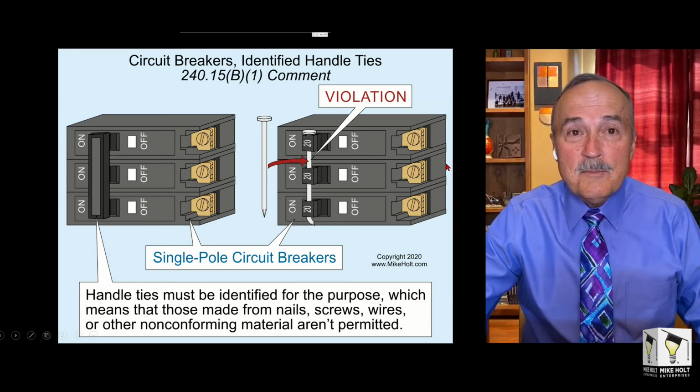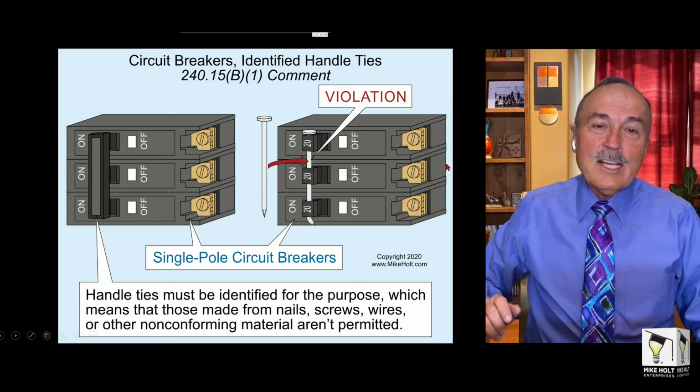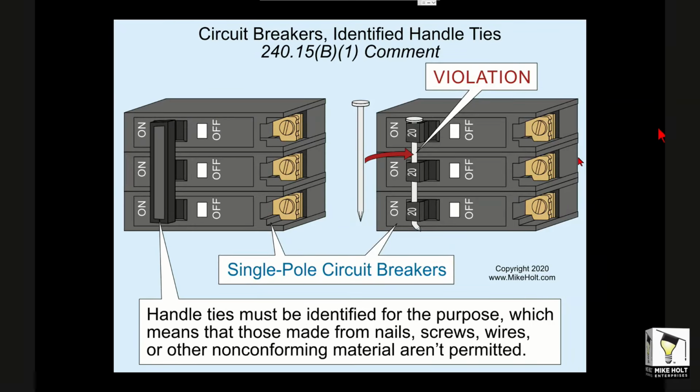Brian, you ready to show that video? All right. Okay, he's going to show that video there. But just so you know, the rule of multi-wire branch circuit is not to simultaneously open under an overcurrent condition. It's to simultaneously provide a disconnecting means to open the circuit.